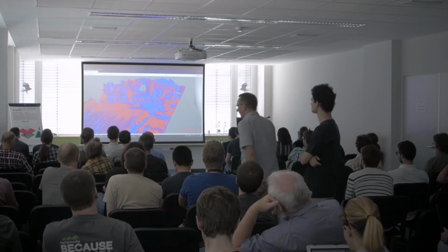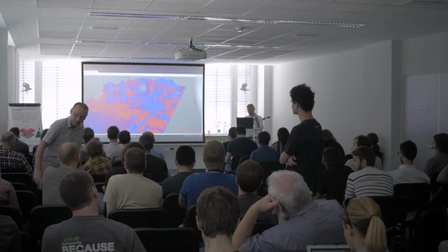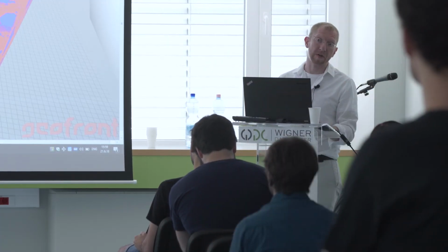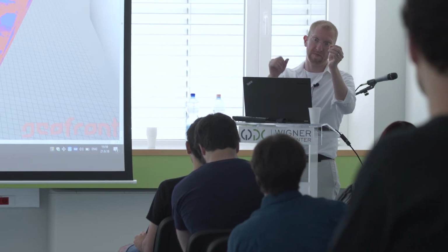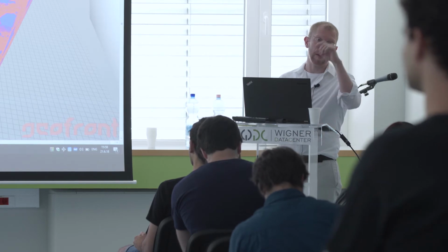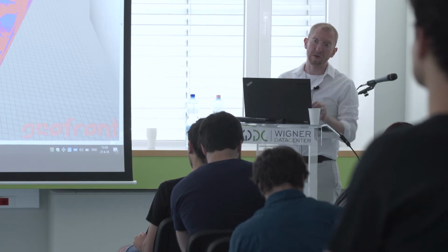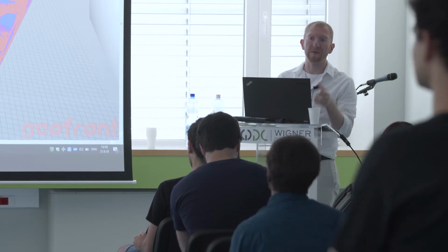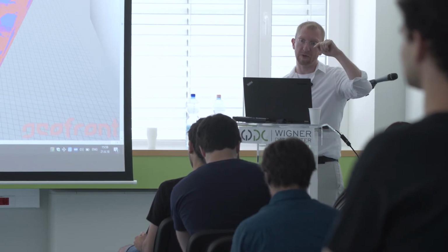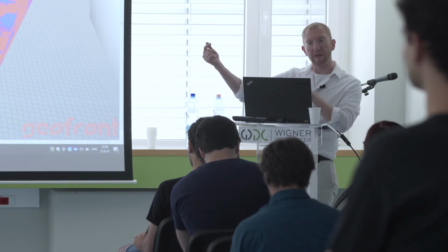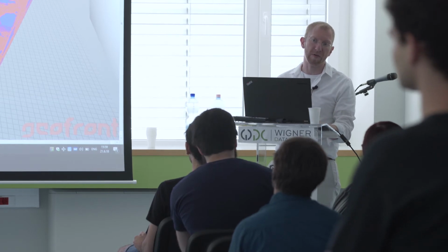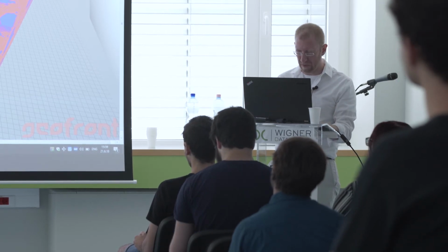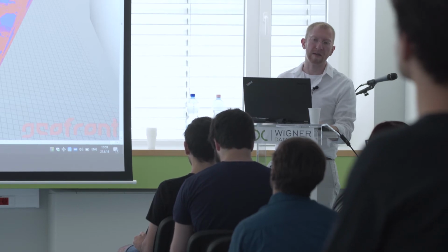But you're right, if you want to compute proper material behavior or similar, you need to take the camera positions that have been reconstructed by the photogrammetry software, look at each texture surface pixel, more or less, and then see which cameras have seen it, and also compute what kind of samples you have from different directions, because you know the original camera position. So this way, combined with the sun position, you can then start reconstructing the material property. I have one link to Vlastimil Hadran in Prague that can tell you more about that.